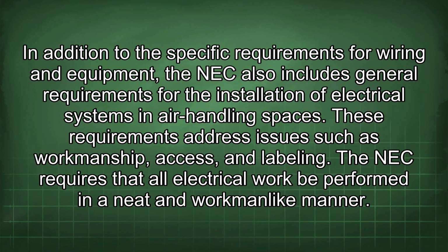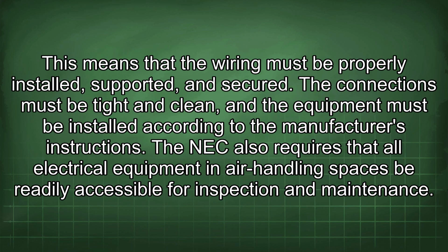In addition to the specific requirements for wiring and equipment, the NEC also includes general requirements for the installation of electrical systems in air handling spaces. These requirements address issues such as workmanship, access, and labeling. The NEC requires that all electrical work be performed in a neat and workmanlike manner. This means that the wiring must be properly installed, supported, and secured. The connections must be tight and clean, and the equipment must be installed according to the manufacturer's instructions.